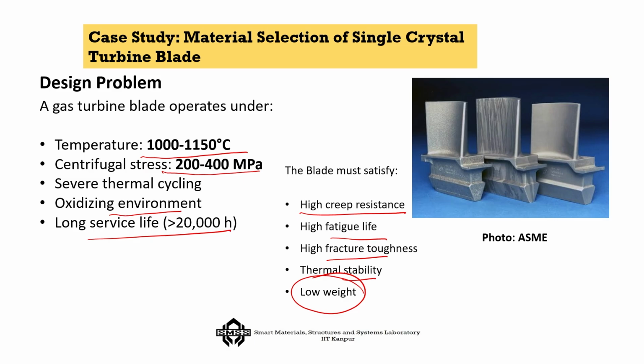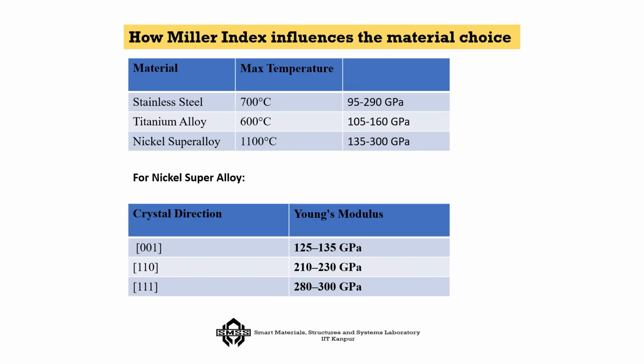So, in such a case, if you have multiple crystals, a polycrystalline system, then as you are heating it up, the grains are going to work against each other, and that will create a lot of possibilities of failures. Hence people want to make it with a single crystal. Like these are single crystal directions. You can see the single directions in some of the cases easily visible.